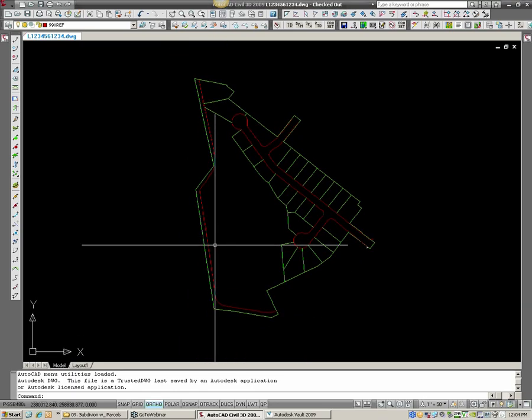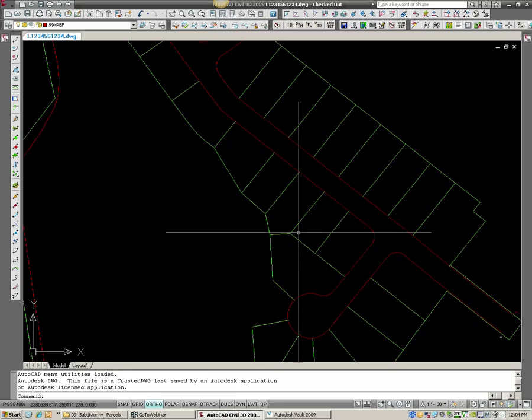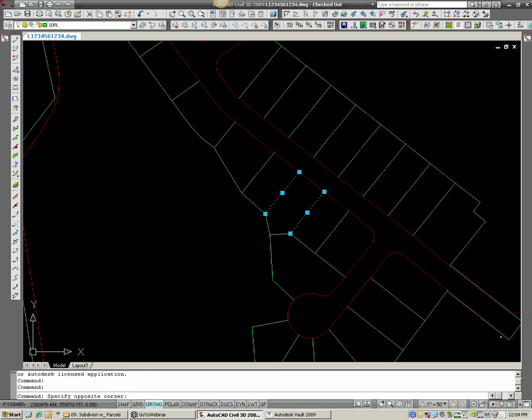In Land Desktop, parcels were never really viewed on the screen. They were sort of a data vessel in the background that maybe made parcels from the polylines, arcs and line work that you had, and you could do a map check or possibly legal descriptions, but you didn't really display that line work. The line work you had on your screen is much like what I have here in this drawing. These are just lines, arcs, and polylines. So they were AutoCAD objects.